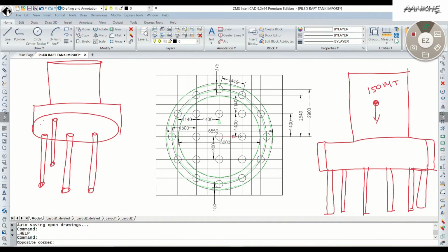So when you go to the calculation of your seismic force, your seismic force is calculated using Z by 2 into I by R into Sa by g.